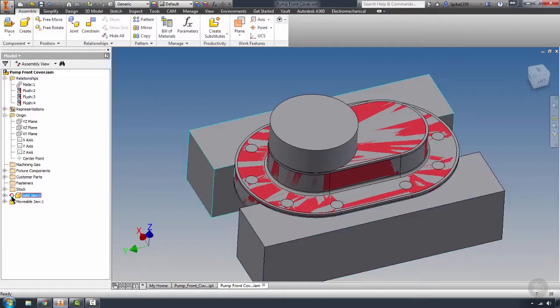Now you'll see this recycling little blue and red icon here. That means that it's adaptive. What that means is if the positioning of the sketch that we created the pocket to the jaws changes in any way, it's linked directly to the part itself. So this is a direct link. Anytime you see this inside of the browser, that means that it's linked to something else, and you need to be careful when moving components around because that's going to update the sketch automatically.